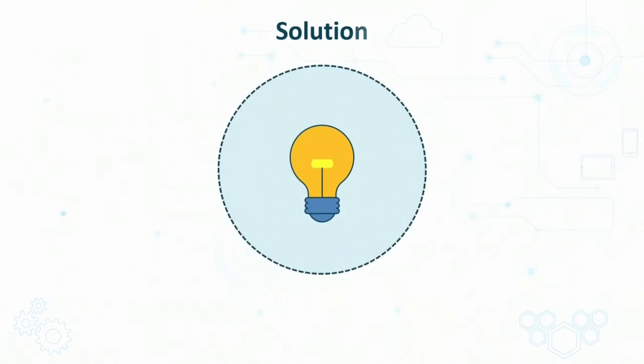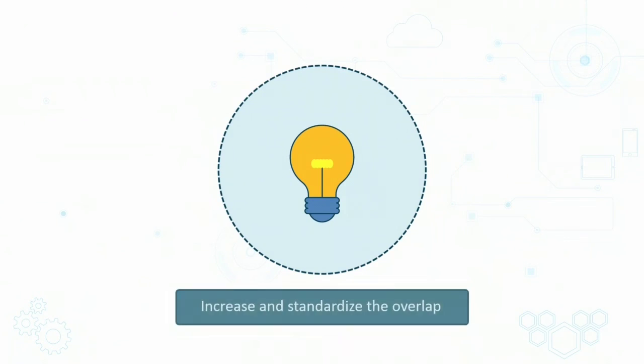The team compared the brazing process in each production line. The tubes on the production line producing units with no leaks stuck out much farther than the tubes on the other production line. Longer tubes mean more overlap and better coverage of brazing material on the return bend. This turned out to be the cause of the leaks. The solution was to increase and standardize the overlap.